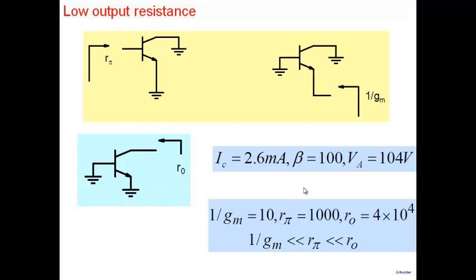So what we see here is that if you are looking for a low output resistance, you should take the output from here, from the emitter, because the resistance at this particular node here, if you look at a resistance at any particular node, it will be resistance looking left here or resistance looking right here. If the resistance looking left is 1 by Gm, already very small, any resistance which is towards the right, whatever value it is there, it will come in parallel with 1 over Gm and overall resistance will get lower. Okay, so this is the motivation for taking an output from the emitter here.